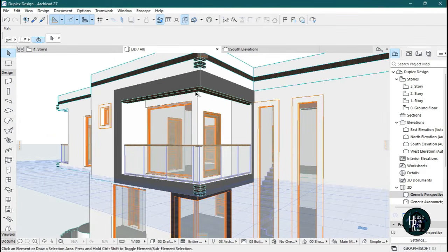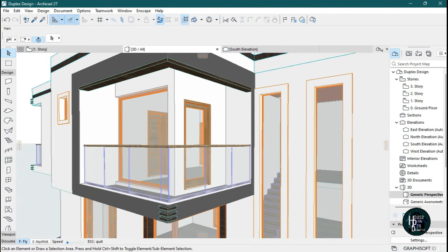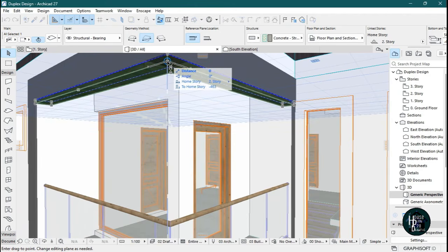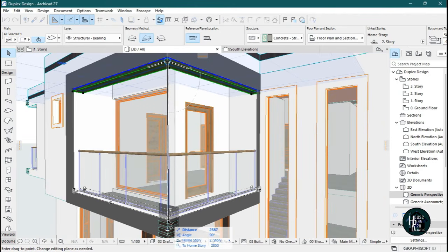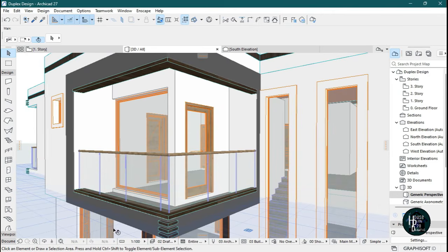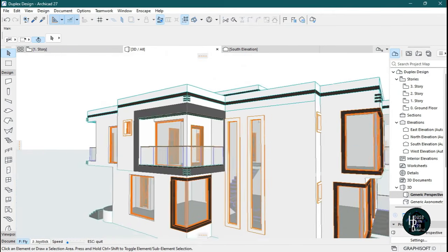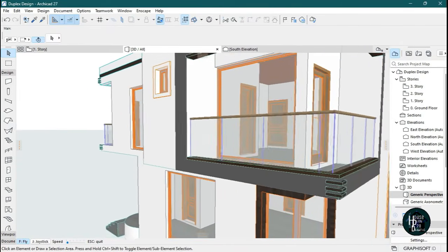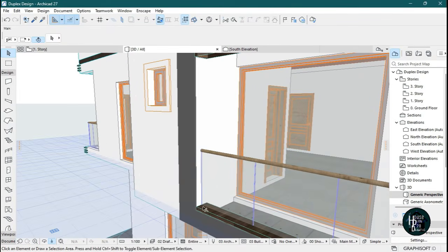All right, so let's copy this and bring it to the base. So if you click on this design we did, press Ctrl Shift D on your keyboard to try and make a copy. Pick that point here, that's this node here, okay, and let's bring it to the base like this. So we have something like this, as you can see. Have something at the base like that, and for this also, we're just going to make another slab and take it to the upper side of the building.